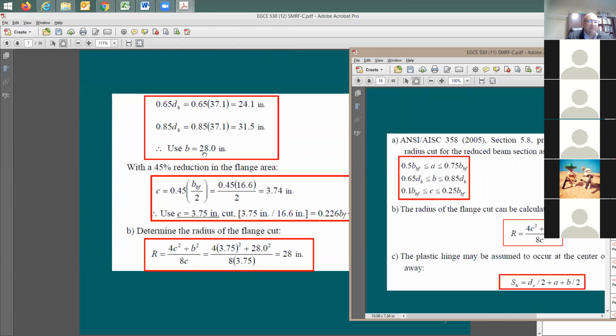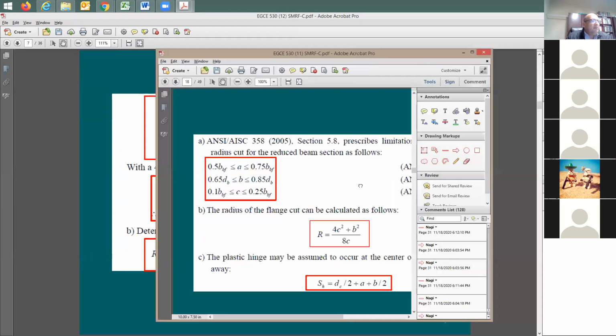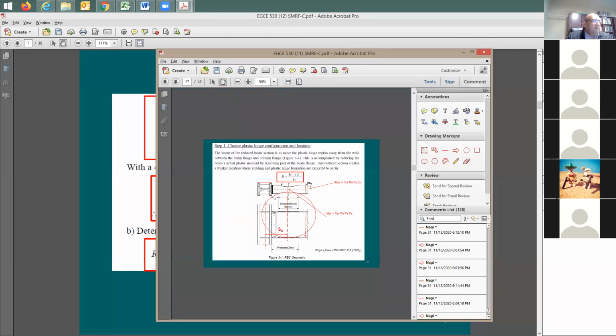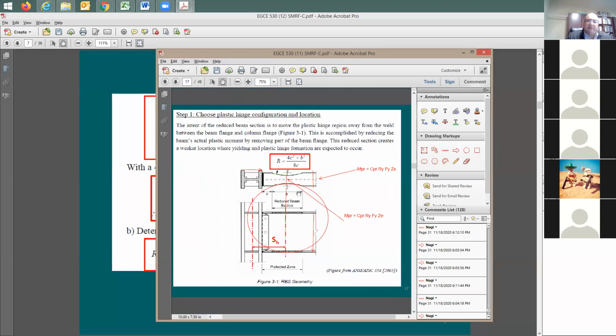The length of the plastic hinge, which is B, because look what happened. If you change the length and make it shorter, what's going to happen? If you make it longer, you are pushing this plastic hinge to the right, which is not good. If you make it very short, you're going to have lots of damage. This is based on performance, not analysis, right?